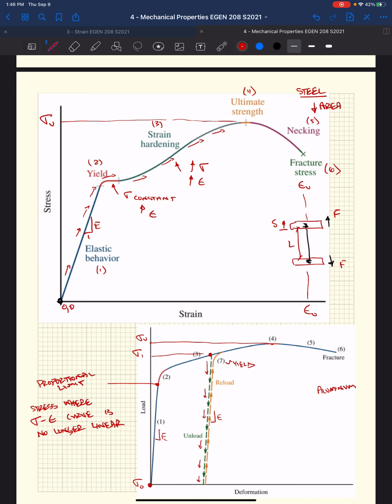All right, so at what stress does our material essentially start to yield, right? It starts our region 2. And this is our proportional limit, right? The stress and strain are no longer proportional to each other, so that's the limit to that proportion, right? One doesn't follow the other in proportion. This isn't a linear line anymore. And that's what you would call our proportional limit. We use that to decide, at what point does our yielding start for our material, which is important.